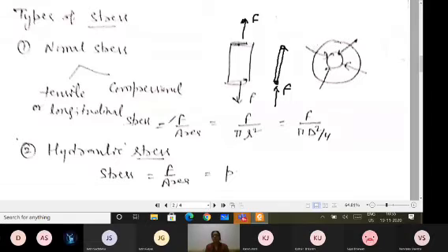So of course, the basic formula is same. So even if the formula for tensile or compressional stress is to be written, you can simply write it as the longitudinal stress also, that is force upon area. And if I'm having a thin wire of radius r, diameter d, of course, because you know diameter of the wire is equal to twice of the radius. So whatever way you can write it in the formula, area is given by pi r square, or you can say pi d square by 4. And units will be same, Newton per meter square.